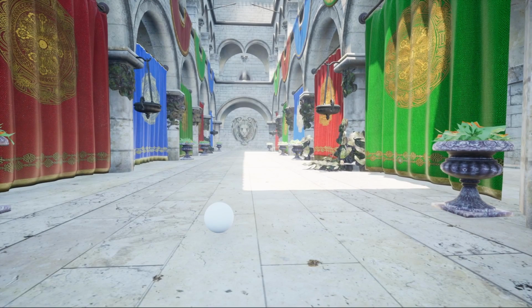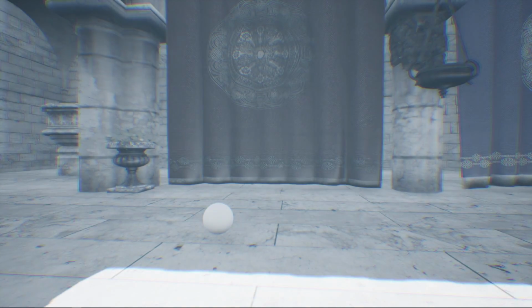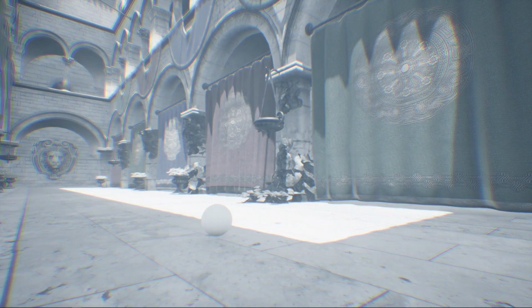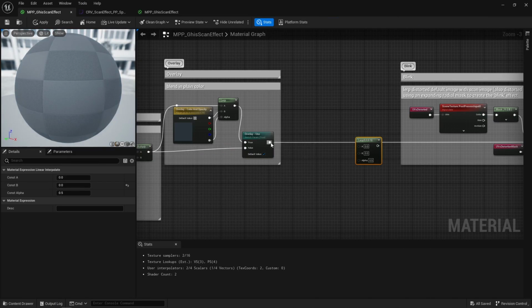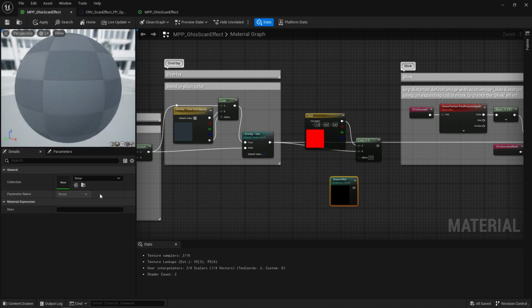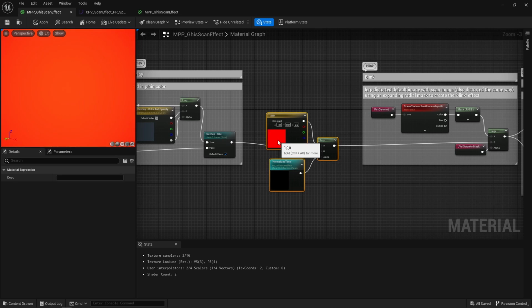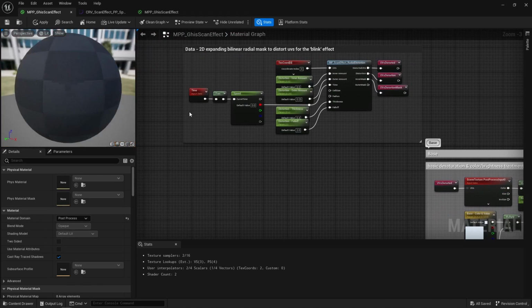Alright, moving on, I'd like for that post-process image to be revealed progressively all around me in 3D space. So I first would like for this blink effect to show a plain background color and only then the world is scanned and revealed on top of it, if that makes sense. So add a second lerp to interpolate between a background color and the scanned image. Alpha is going to be that normalized time for now, just to see what we are dealing with. And actually, let's replace these other time placeholder nodes with this normalized time parameter as well.